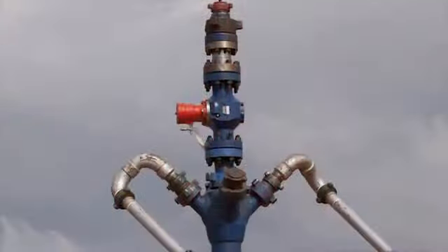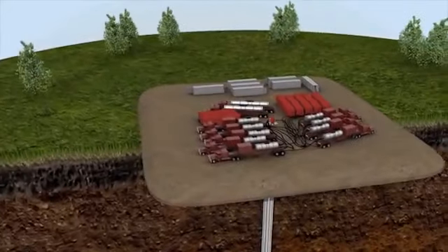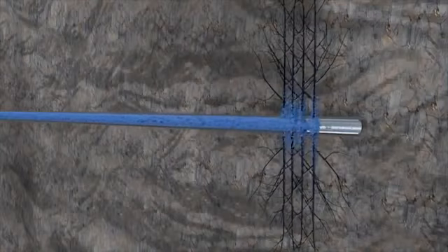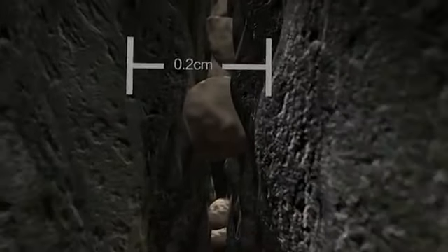These chemicals typically range in concentrations from 0.1 to 0.5% by volume and help to improve the performance of the stimulation. This stimulation fluid is sent to trucks that pump the fluid into the wellbore and out through the perforations that were noted earlier. This process creates fractures in the oil and gas reservoir rock. The sand in the frac fluid remains in these fractures in the rock and keeps them open when the pump pressure is relieved. This allows the previously trapped oil or natural gas to flow to the wellbore more easily.